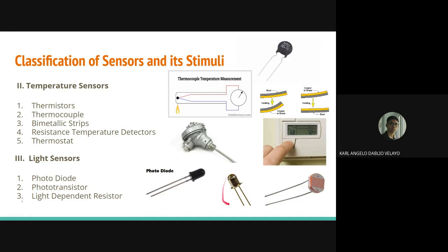Next, we have the phototransistor. So looks similar to the photodiode. So this is an electronic switching and current amplification component which relies on exposure to light to occur. So it is commonly used to detect light pulses and convert them into digital electrical signals. And for main applications, commonly used in punch card readers, security systems, and encoders.